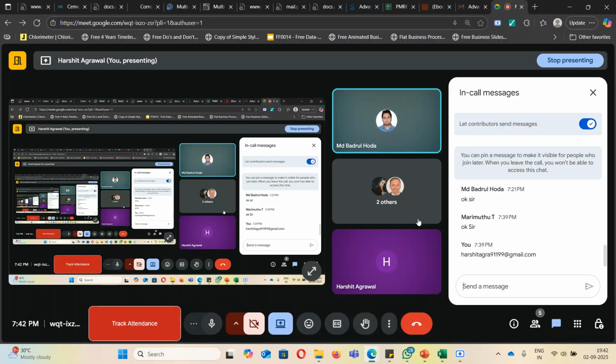Then this section is called what? Is it under reinforced or over reinforced? This is an under reinforced section. Why? Because yielding on the tension side is governing the design. Okay, sir, that is what you are asking.